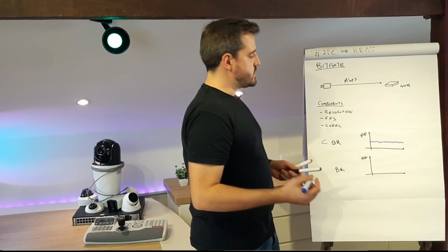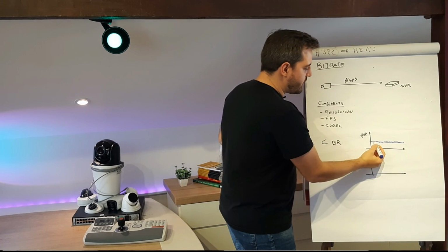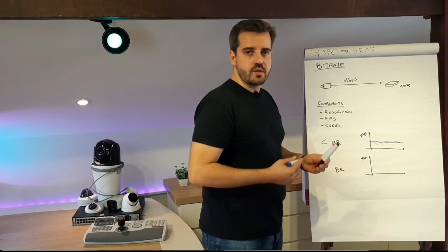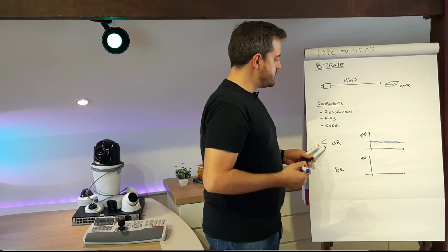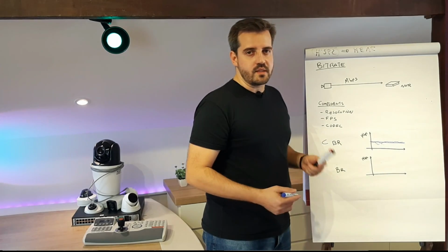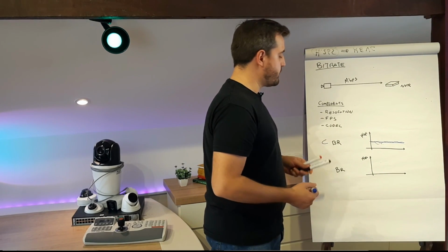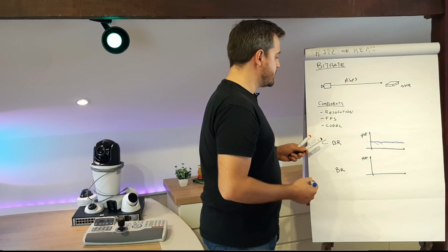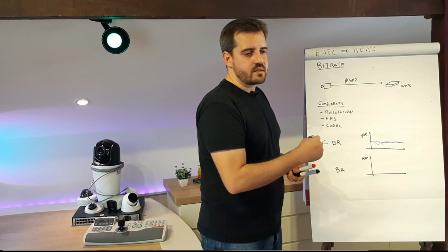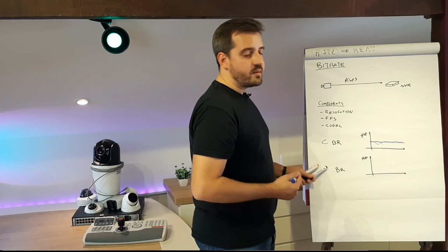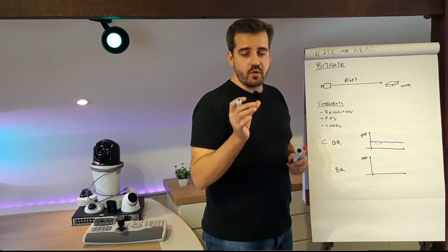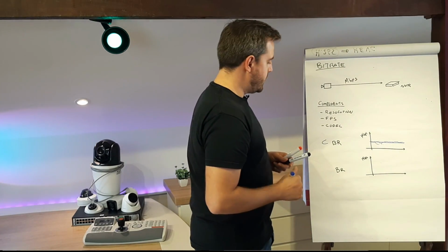But the con is that we are not gaining the benefit of the codec, which, depending on the scene, would decrease the information sent by the camera. So it is not ideal when we start to use H.264 and H.265. It really depends on each project or need, and on the NVR. If you have a third-party camera on that NVR, not the same vendor, it will not support VBR. It will only support CBR. So this will vary depending on the equipment you have on site.